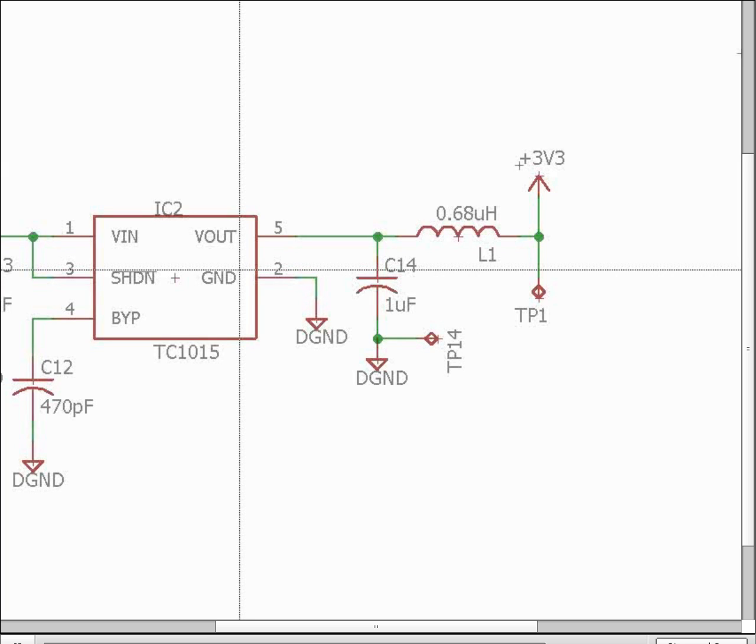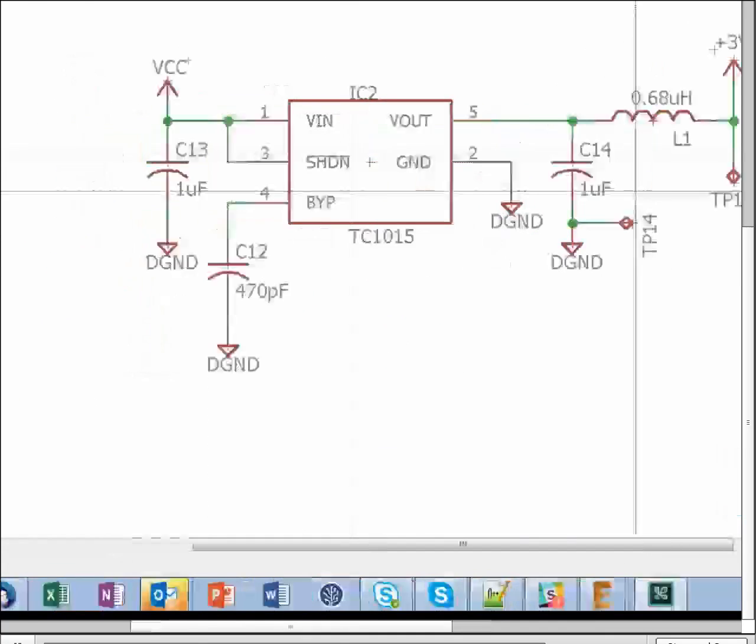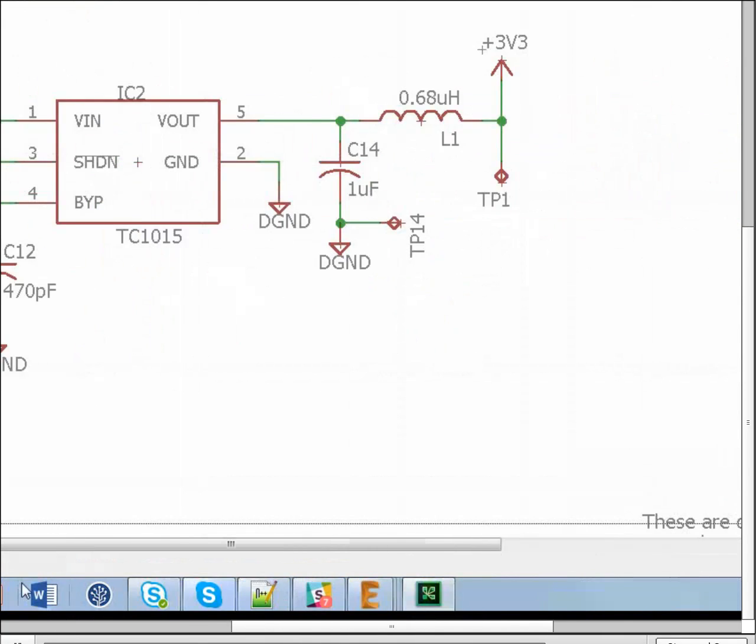So Michael has a question in regards of having DRC regulations for flex as well as for rigid boards. Well, right now, in DRC, you can load different settings, but it only works one at a time. So simultaneously, no, they don't work right now. So you would have to load them separately. You would click on the load command and load whatever DRC settings you wish to use for your rigid side, and then you would have to load the other DRU file for your flex side.